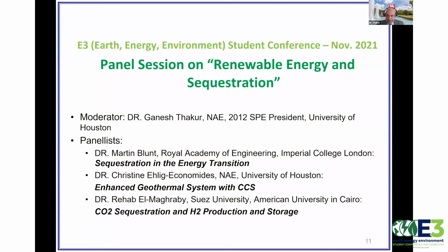CO2, even mixed with a little bit of water, is a carbonic acid. So corrosion and scale, you have to watch. You have to design your equipment in a careful way. But as Martin pointed out, we made sure that we never went above the fracturing pressure or the original reservoir pressure in the reservoirs, so that we did not create any kind of additional communication out of the reservoir. So pressure monitoring and injection profile control were the two most important things for the surveillance and monitoring of the CO2 EOR injection projects.